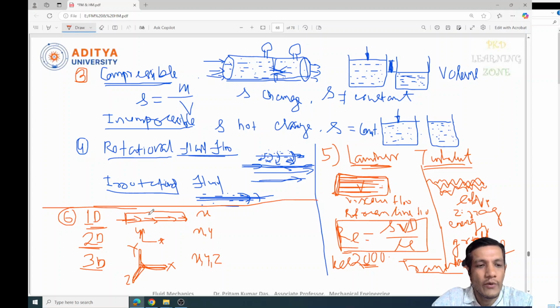Now how can we write the one-dimensional flow? One-dimensional flow is nothing but a flow in which the flow parameters, such as velocity, if you consider the velocity, is a function of time, and it's moving only in one space coordinate. As I told you, it's moving only in one space coordinate. Space in the sense only along the length. Suppose you consider only one space coordinate,